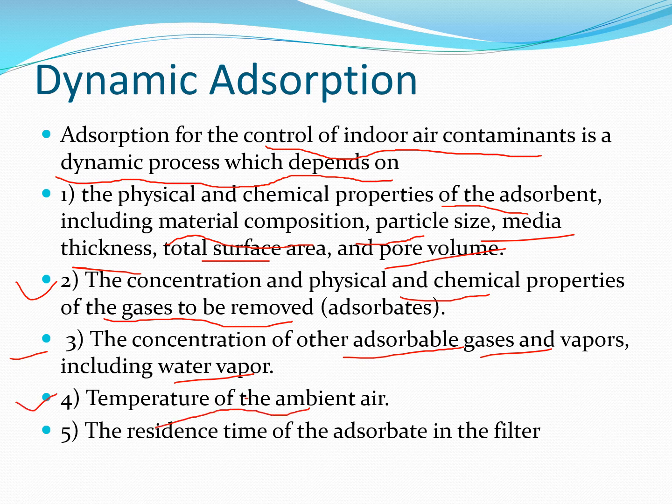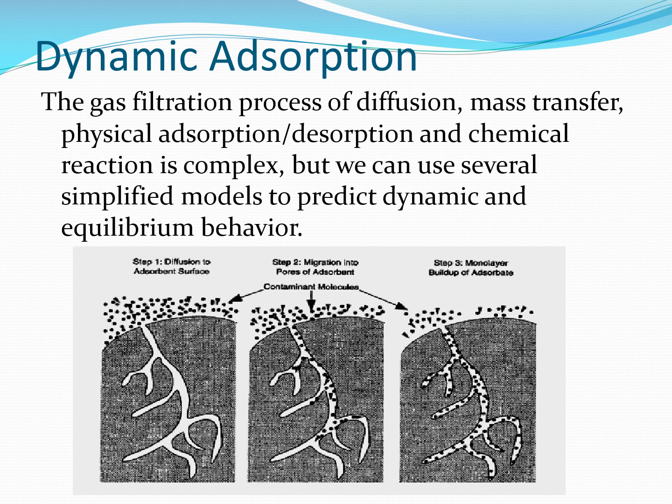These all are the factors that affect the adsorption phenomena, along with the residence time of the adsorbate in the filter. So the gas filtration process of diffusion, mass transfer, physical adsorption, desorption, and chemical reaction is complex, but we can use several simplified models to predict dynamic and equilibrium behavior.